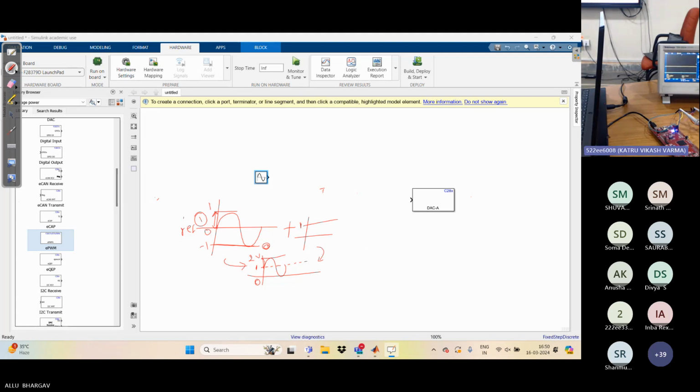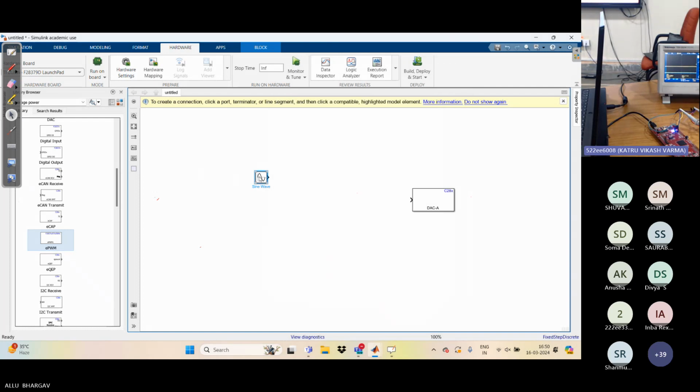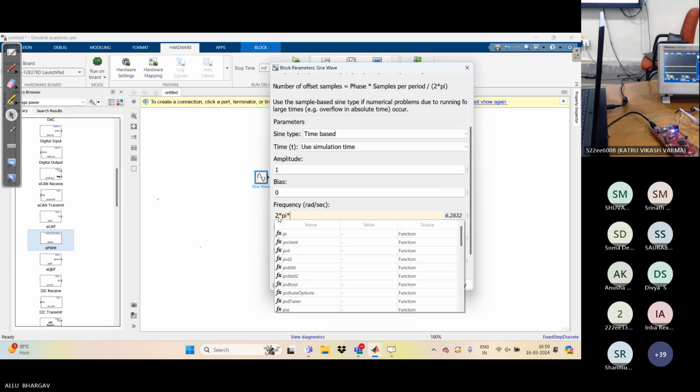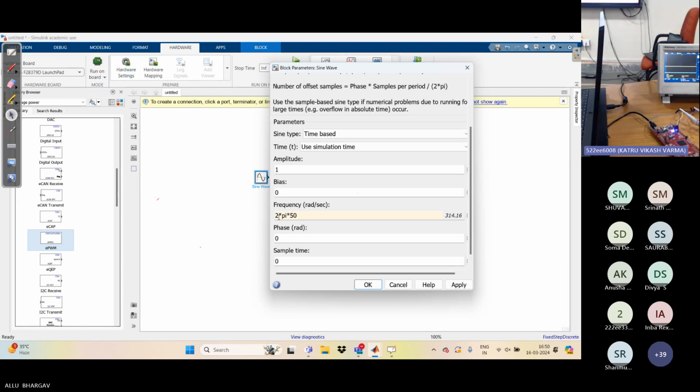So we are giving the signal now. How to add this additional DC value in software? Let's first define the sine, then we'll go to how to add it. So I'm giving 50 as the signal frequency, and I'm giving a sampling time of 5e power minus 5.